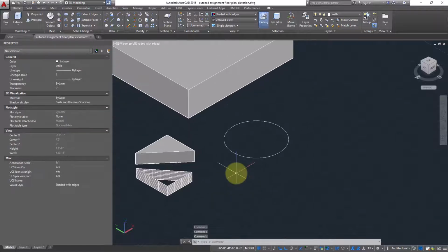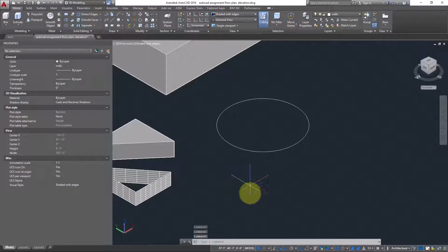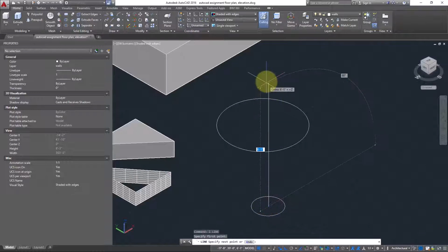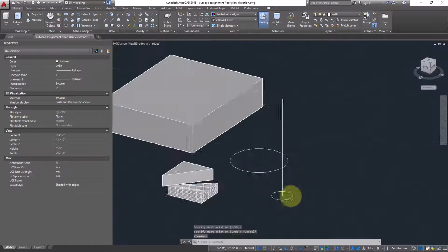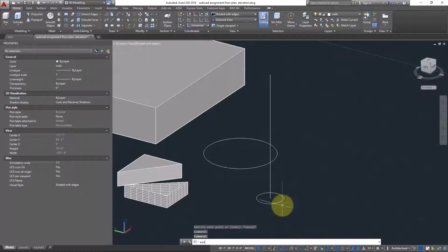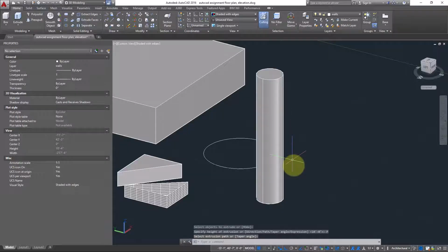We have more options also in the Extrude command. If you have one circle, for example, like this, and a line, the line should be perpendicular to it. I will make it along the Z axis with ortho on. Yes, it's on. I'll check that it is perpendicular to the object. Now if you go to EXT extrude and enter, select the object to extrude and enter, it will ask you many options in the extrusion. This time we will select path, click here and select the path. Now you will see the extrusion is done along the path.